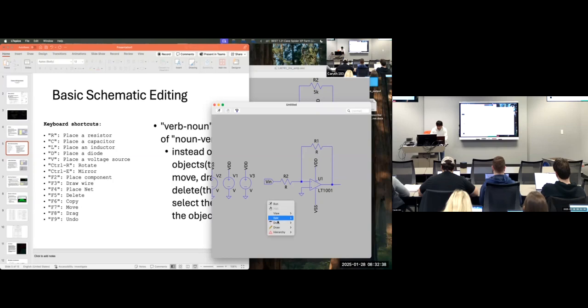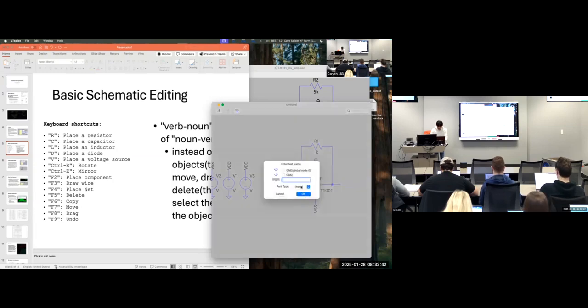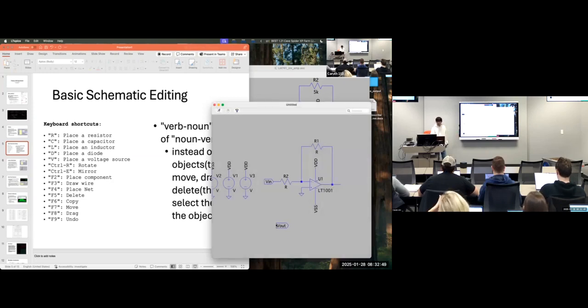Now I'm going to do the exact same thing, but for v out. So draft, net name, v out. Port type is obviously an output, since it's going out of the amp. The only difference between the input and the output flag is that they both look the same, except the little triangle parts are on the input side, specifying that it is input, and the output is the tail end.